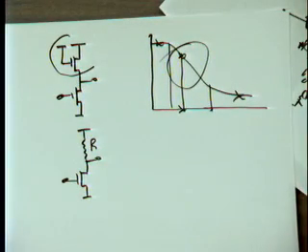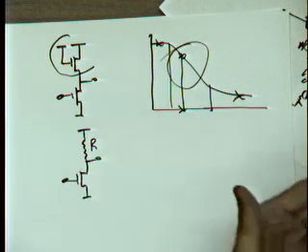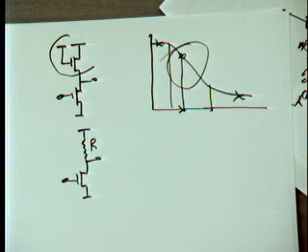That's something I can recognize. So even if I drive it away into something which is undefined, it still ultimately will go to one side or the other side, and you will have a deterministic signal. So undefined only for several stages. Finally, it will be defined, and it's fast. If you have a gain like 10 or 100, something like that, CMOS inverters have a gain of what? Approximately 15. That typical number, 10 to 20, is the range of a normal CMOS inverter.